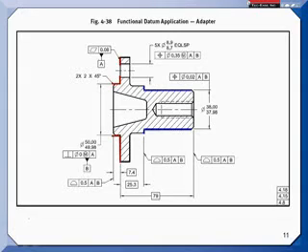Then the CMM was probing the true pos pins to determine the axis. And by the way, the tolerances were projected out of the hole because you're worried about where the screw actually ends up. So when they were inspecting the true pos pin, they were inspecting the projected tolerance zone.